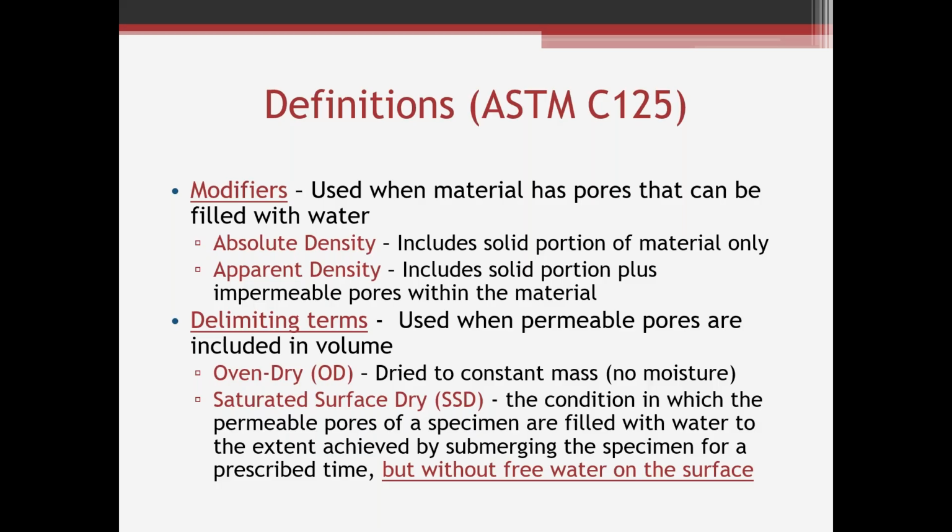And your saturated surface dry density, which is probably the most common term used in the concrete industry. That's a condition where all the permeable pores are filled with water after it's been submerged, but there's no free water on the outside surface. So it might look damp, but there's no water dripping off of it, and all those little microscopic pores are filled with water.